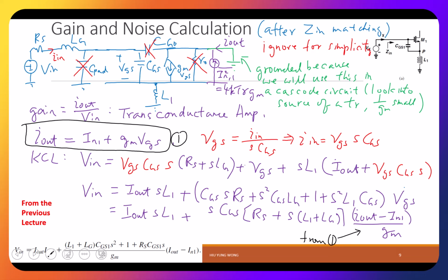So this is the major one we have been playing with. It's 4kT gamma gm. Again, when you talk about noise, we talk about power spectral density, right? So it is square bar. So the unit is ampere square in this case, right? So what we did last time is that, okay, I say we may have Vin, we may have noise, we put them together. This is just like one stone, 2 birds. You can actually do it 2 times. I just follow the approach from the textbook. They try to derive everything at the same time.